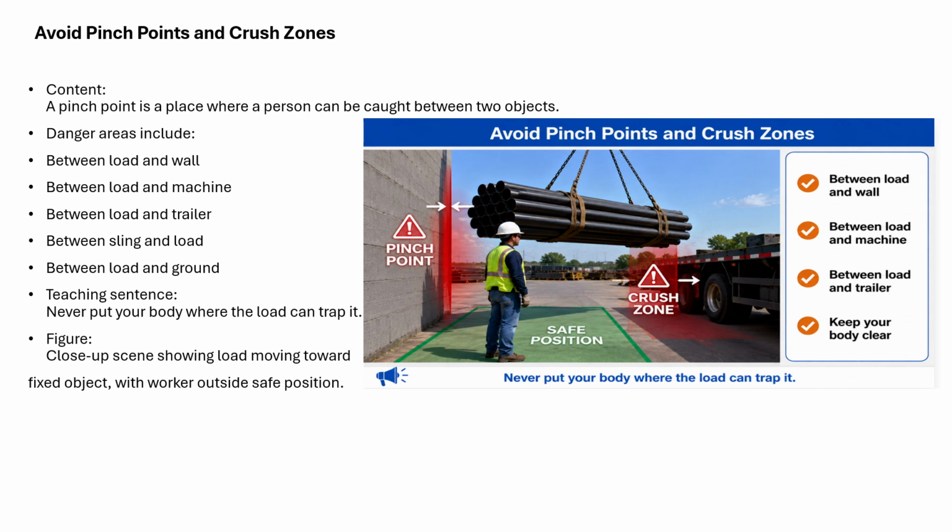Avoid pinch points and crush zones. A pinch point is a place where a person can be caught between two objects. Here is the load and the wall. Danger areas include between load and wall, load and machine, load and trailer, sling and load, and load and ground.